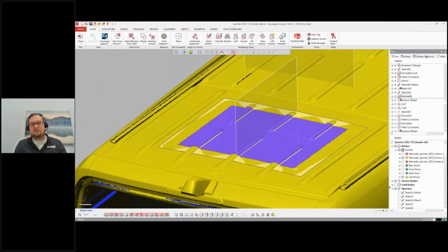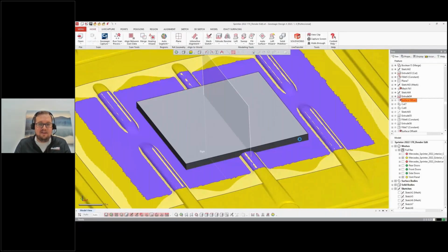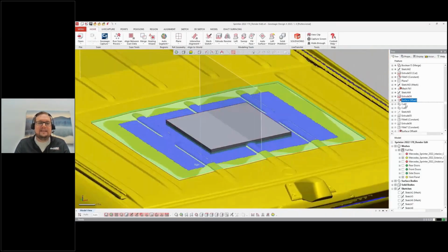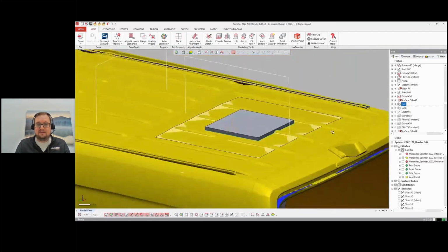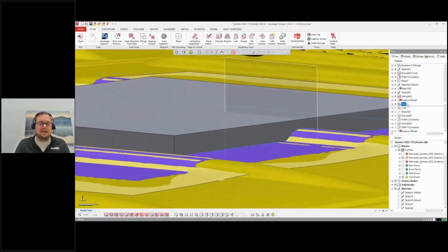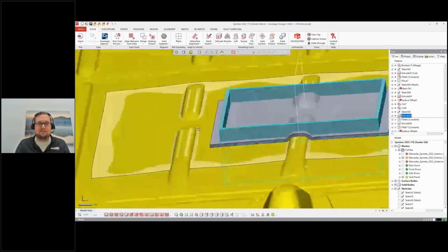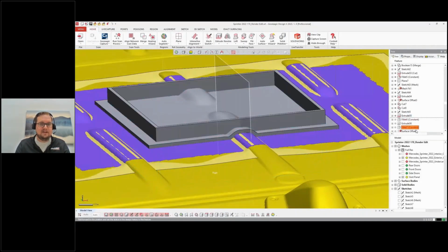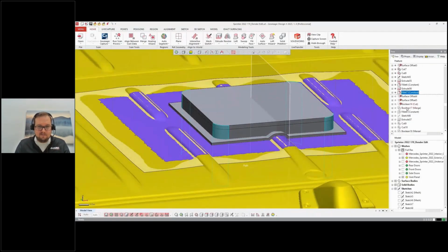So whether you're an industrial designer, manufacturer, or a hobbyist, and you want to create a unique part that fits this specific vehicle, the mesh fit is really a great way to do this. So this, like I said, gives us our shrink wrap feature here, gives me a very, very tight seal to the surface curvature of this. I can use that just as a regular surface like any other CAD feature. I can offset it like I've done here. I can use it to cut solids. I can use it to trim to other features.